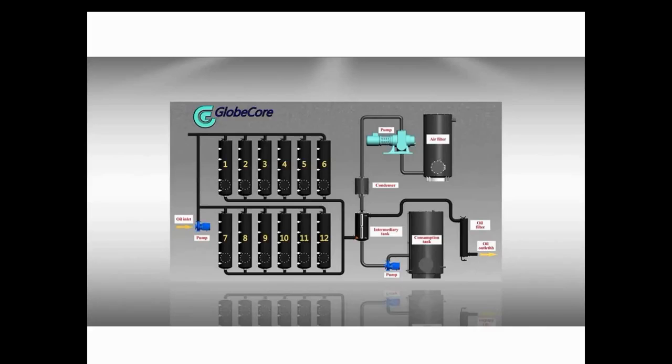Plants can be stationary or mobile. Both types can operate on an energized transformer. But if there is a safety issue in a company or in a country, how effective can they be on a de-energized transformer? Regeneration is up to date the most effective way of oil treatment, aiming at oil usage again in the same or alike electrical equipment. There are no restrictions for regeneration cycles to be executed.